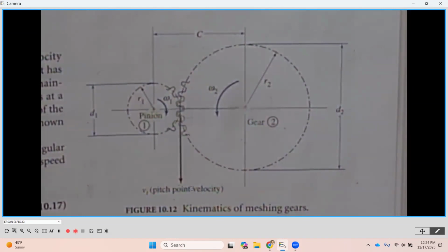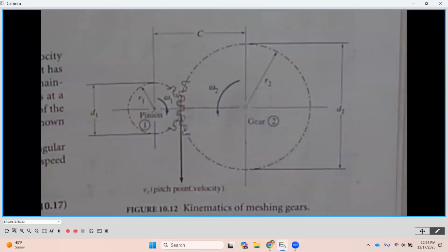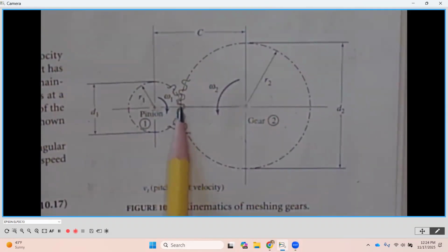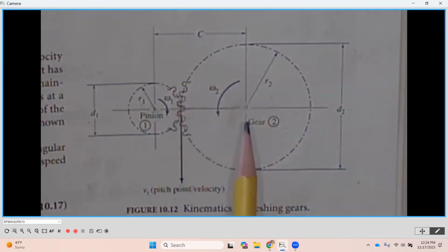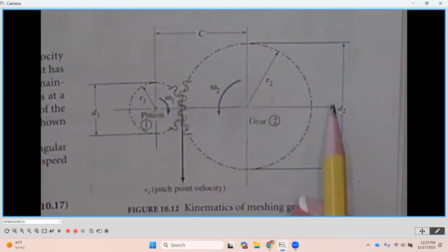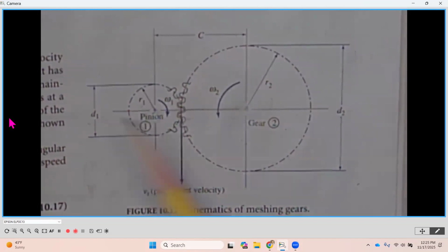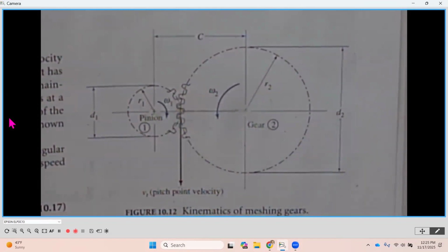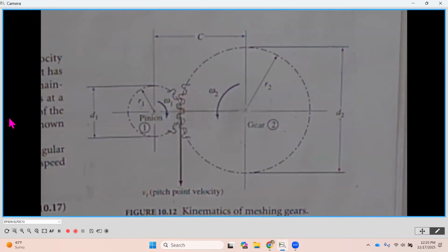They're the physical place where each one of these gears is going to engage and push past each other, and all of the force and the rotational motion is actually going to move through that pitch diameter. Okay. So this also fully defines the extents or the physical size of each one of these gears. So center distance is from center to center, but then the pitch diameter gives us the bigger picture of how much space this is going to take up. So pitch diameter is what we call the tangential diameters or the effective diameters for when they're actually engaging with one another.